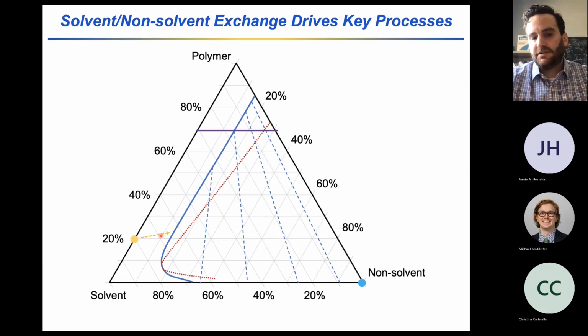And so you begin to take some trajectory into the middle of the ternary phase diagram from the left edge where your casting solution was. And the angle of this trajectory depends on a lot of things, but in this case, imagine we go along this trajectory. And as you continue along that trajectory, then you can plunge through the cloud point or the binodal curve.